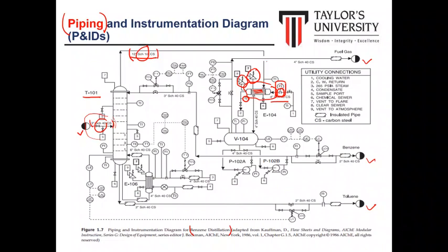And then after entering the tube heat exchanger, it will move into vessel V104. The piping is 4 inches, schedule 40, and the material is carbon steel. For this vessel, it is mounted with LE, the level element. So we have a level element here.